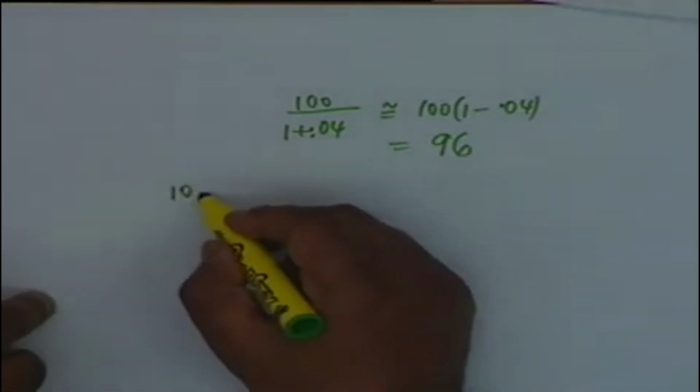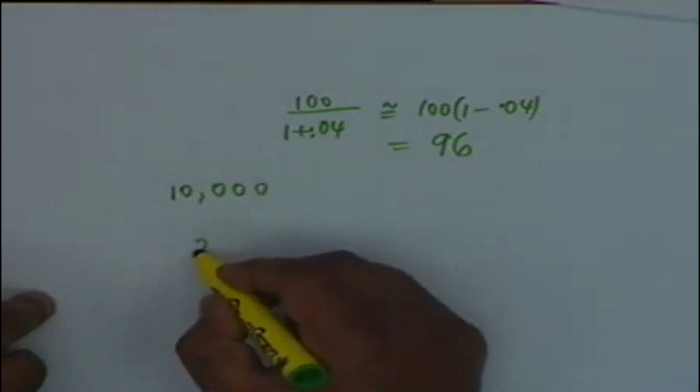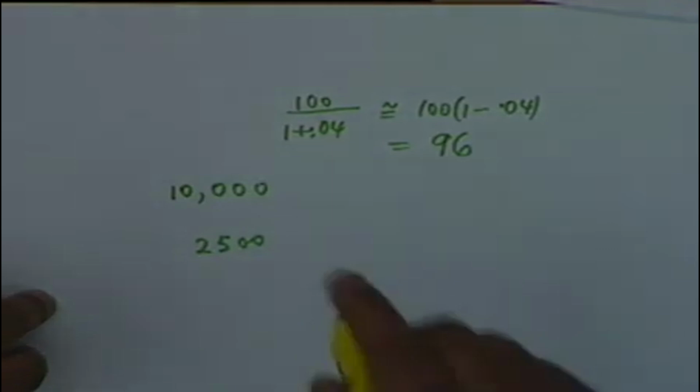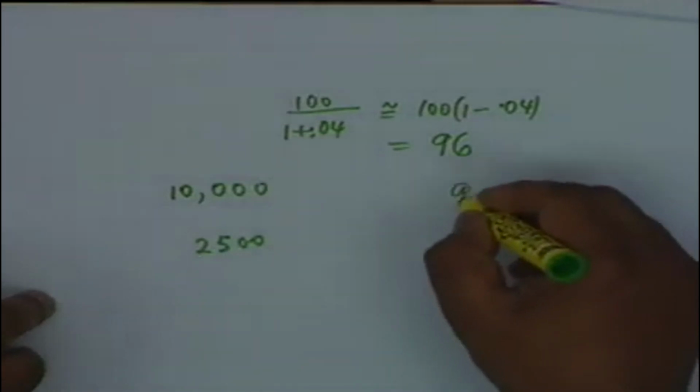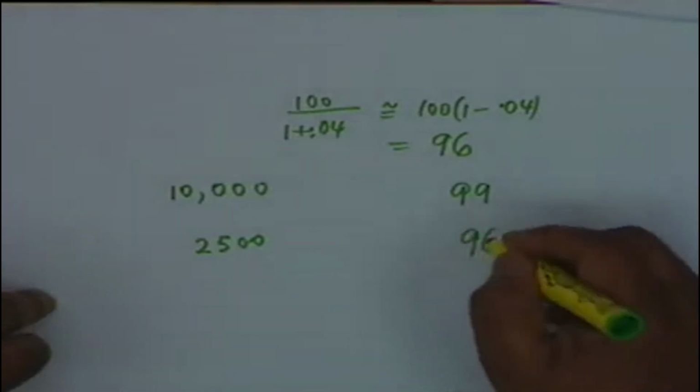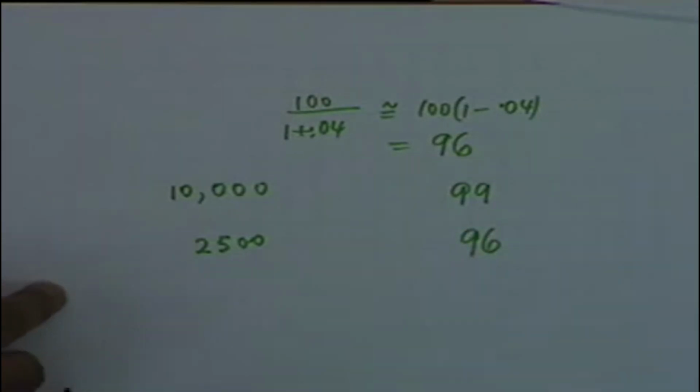So a gain change from 10,000 to 2,500, a change by 75%, makes a change in the feedback amplifier gain of only 3%, from 99 to 96.